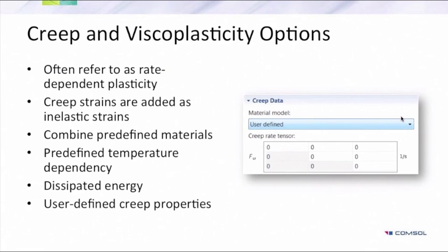For creep and viscoplasticity, basically those models are quite similar. In viscoplasticity there will be some hardening, and in creep there will be no hardening. Those two names are used, but numerically those two models are very similar.